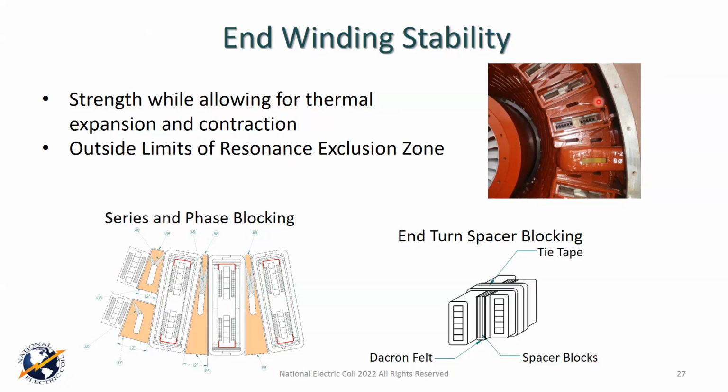Usually it's one or three. And in three pieces, you pull them together with the taper, and then you lace them all together, and it works out quite well. And obviously, this is a hydrogen-cooled winding. You see the hydrogen-cooled tubes in here. We can see this phase lead has a big hydrogen passage to allow the hydrogen to go through its path and to do its job. So I hope that helps you out just a little bit.